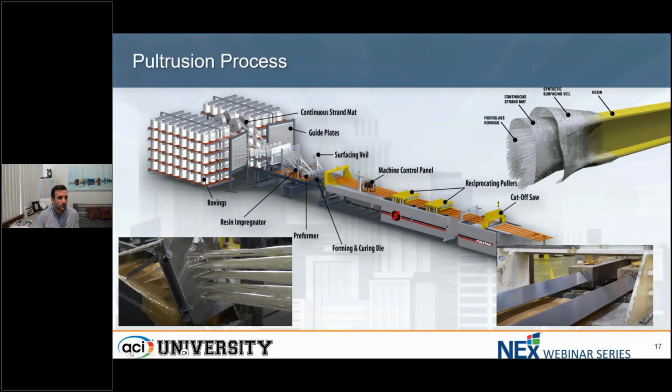And if you're not too familiar with the pultrusion process, this slide gives you an overview of what it is. Pultrusion, because you're pulling those fibers through, not unlike other FRP type of systems. And as you pass those fibers through the saturating resin, and you align them, and you have this constant tension of the fibers. On the other side, very important, goes through basically an oven where the resin is baked. That resin structure crystallizes in order to give the FRP pultruded element those structural properties.